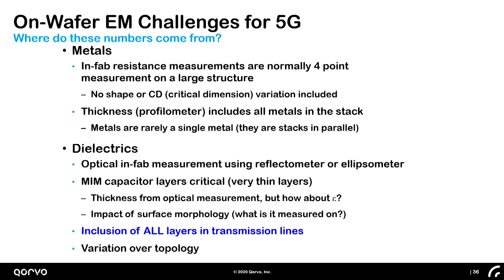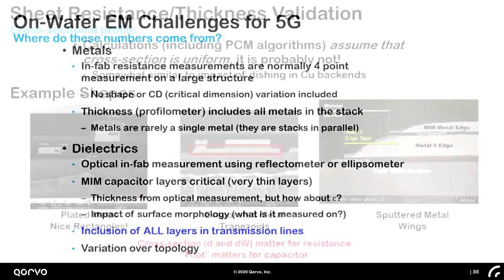And the other thing is, as we go to higher frequency, I would say almost nobody's PDK includes all of the dielectric layers that are on the wafer in the EM stack. They usually take some estimate and just say, oh, they only need from here. And it's not really true. At higher frequencies, you need all of it, and the variation over topology.